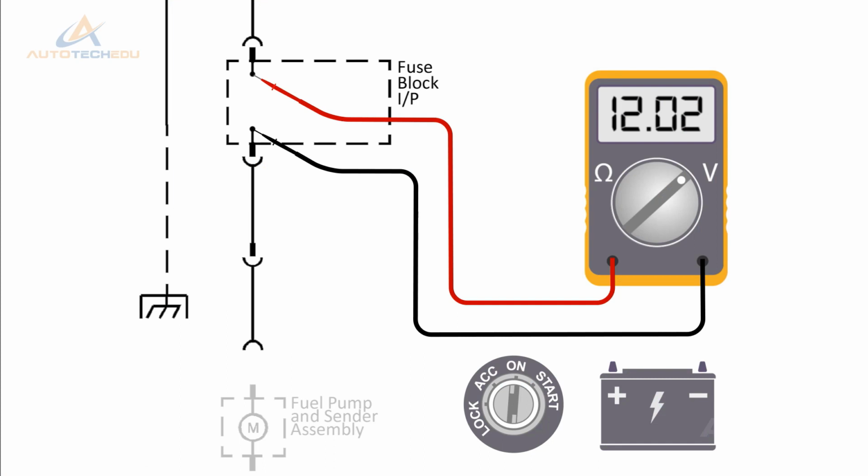Locate and disconnect the next connector in line while observing the meter. If the meter now displays 0 volts, then the short is in the disconnected section of harness. If the meter still displays voltage, continue unplugging connectors until a change in the meter is observed. This will isolate the short to that section of harness.